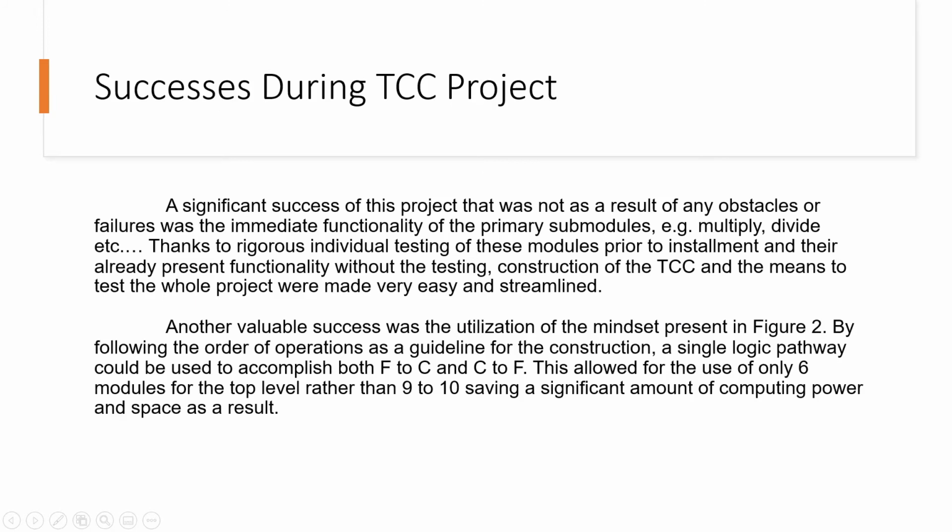Now before we finish, I'd like to go over the successes that I achieved during the TCC project. One of the most significant ones was the independent functionality of all submodules prior to the top-level module. The multiply, divide, add, subtract, positive to negative, and initializer modules all worked independently of each other prior to being compiled together. As a result, this made work significantly easier on the project, and the reason behind their functionality prior to installment was vigorous testing beforehand.